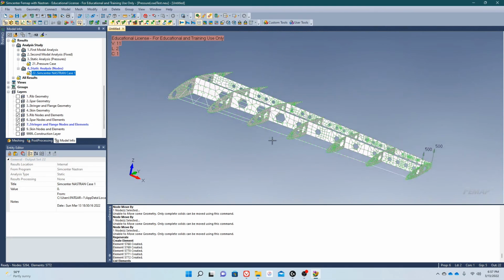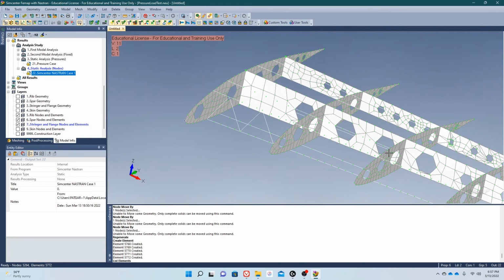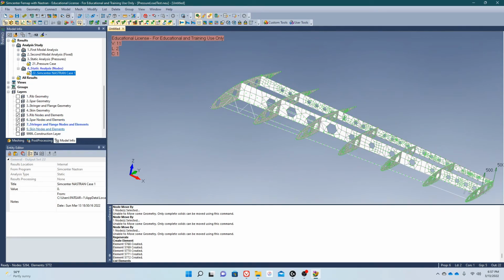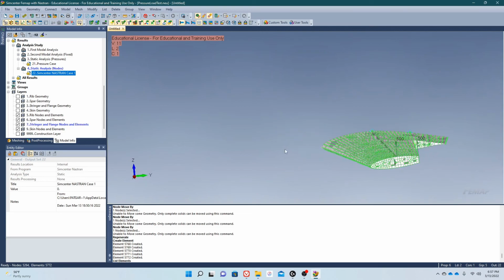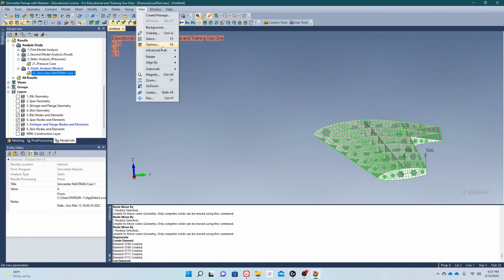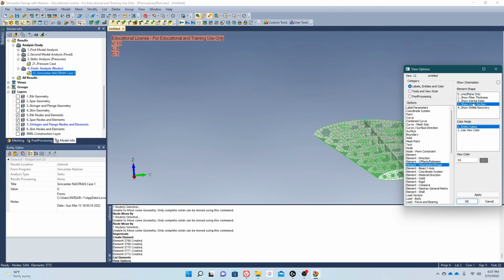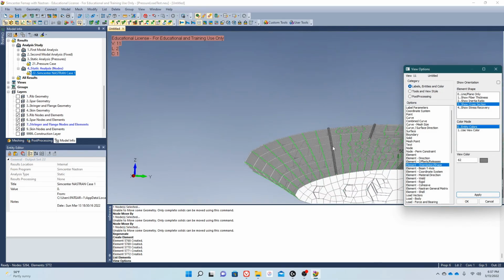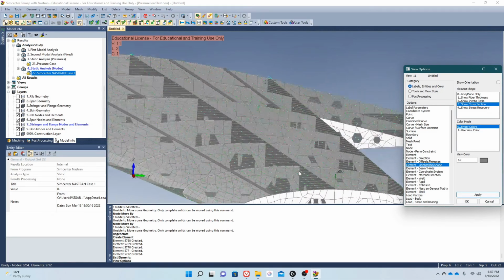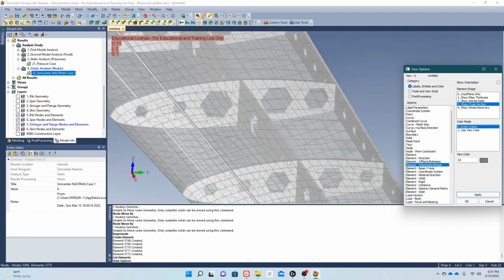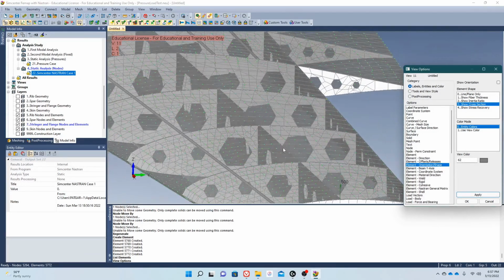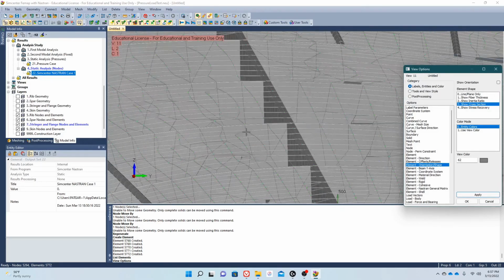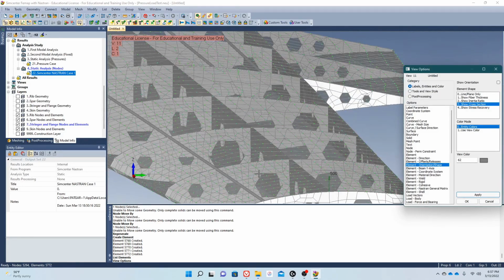Now one final thing, now that we have all of these elements created for our internal structure, is that we want to view this as a thick structure. If we go to element orientation shape, we can turn on the cross section for all of our elements, and our stringers will show a lot easier than they were just showing. Our ribs and spars will have a certain thickness as well as our skin, although it is more noticeable for the ribs and the spars because they're not transparent like the skin is.